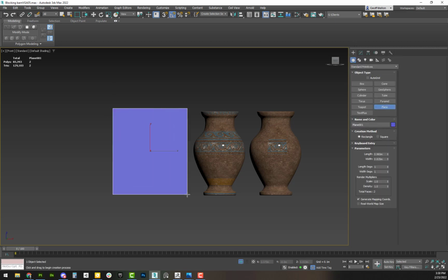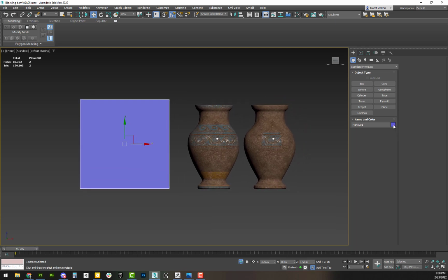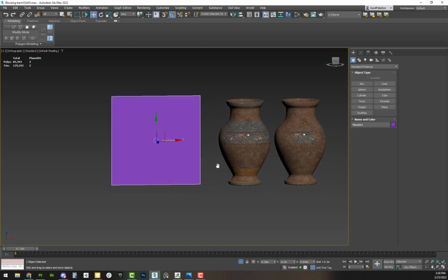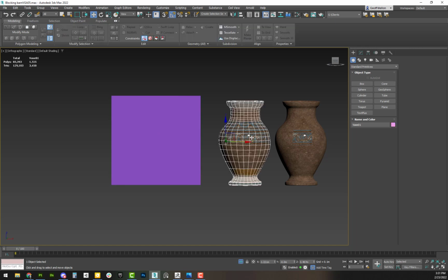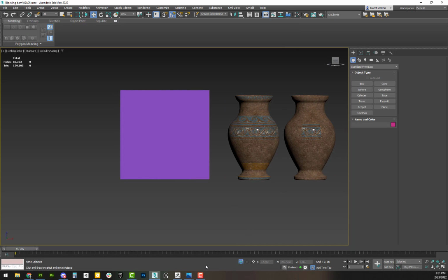We just want to make sure it's simple and completely square so the maps will work on it. So I'm just going to go one by one to make my life easy. It's probably bigger than it needs to be if I'm doing the right ratio for the texel density, but that's fine. And then we're going to come into here. It's funny that it picked what looks like a normal color, so I'm going to pick something a little bit different. Okay. And there's two ways you can put decals into an object, but both ways you're going to do it with the object having another material on it for this, and that inside of Unity.